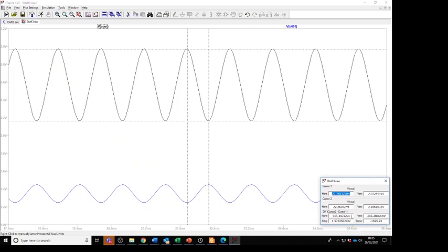Is the phase shift caused by delay? No, the phase shift is caused by the fact that the gain is negative. It's got an inversion in the gain. So it's a gain of -4. Remember, the slope was negative, so it went down. So that's what's causing the inversion.